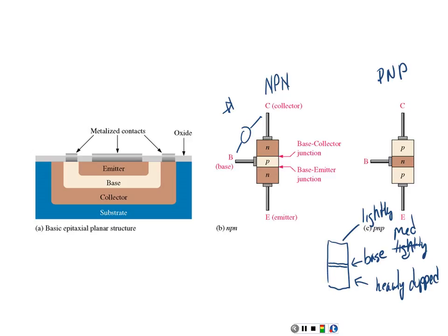And this is the way we check a transistor. We check it with an ohm meter. And if I come over here and put an ohm meter right there and put my black lead toward the N and my red lead toward the P, it's going to measure approximately 0.7 of a volt if it's silicon. If I come over here and put my meter across the emitter and the collector, what do you think it's going to measure?